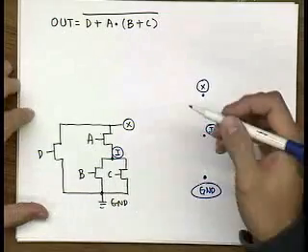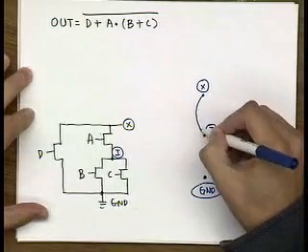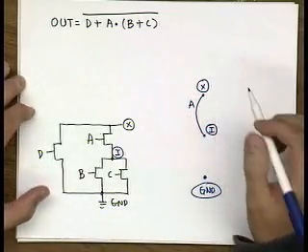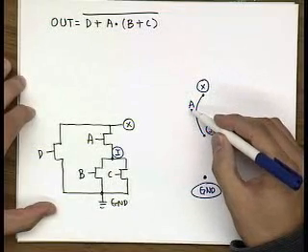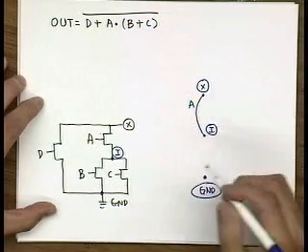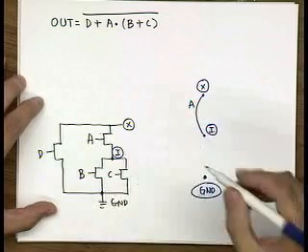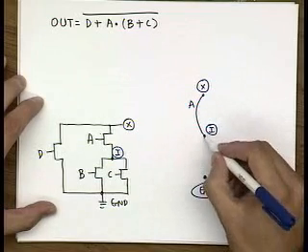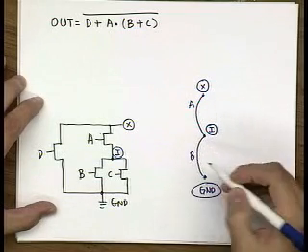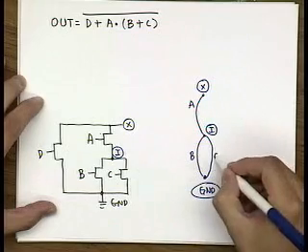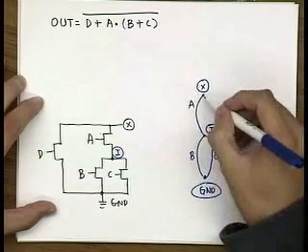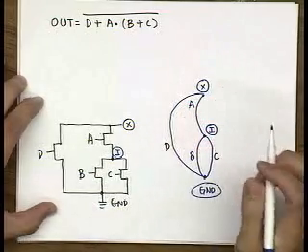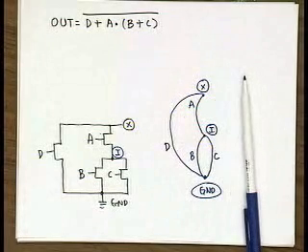So basically, you connect X and I when your input signal A is active, which makes sense. Basically, you are connecting these two on a condition that A is high. And then you do the same thing for the other transistors. So you basically represent each transistor as an edge of this graph. So you have now signal B over here, and then you have C for this transistor, and then I finally need to connect these two, D. And this is my pull-down network.